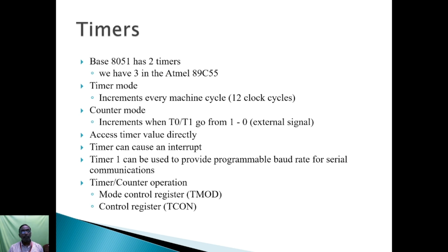For example, in an application, we fix an ultrasonic sensor at a door. When 10 members cross, it generates 10 pulses. That is given to the counter and it counts that 10 members are inside the room. So this is a small example of an application using an Arduino microcontroller.